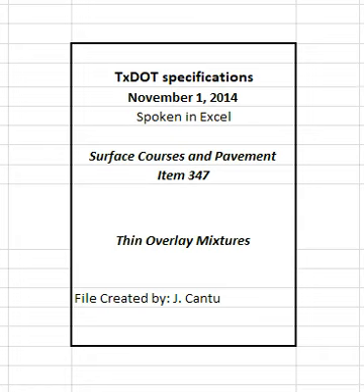Take immediate corrective action if the engineer's laboratory molded density on any sublot is less than 95% or greater than 98% when using the SGC, or less than 96.5% or greater than 98.5%, to bring the mixture within these tolerances. The engineer may suspend operations if the contractor's corrective actions do not produce acceptable results. The engineer will allow production to resume when the proposed corrective action is likely to yield acceptable results.